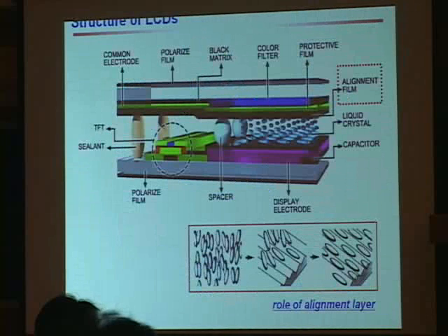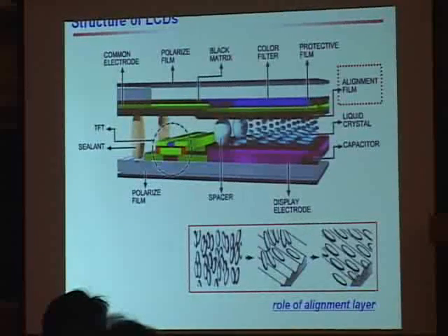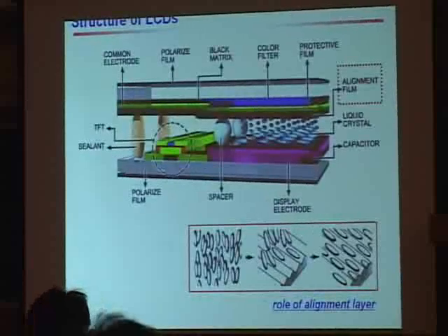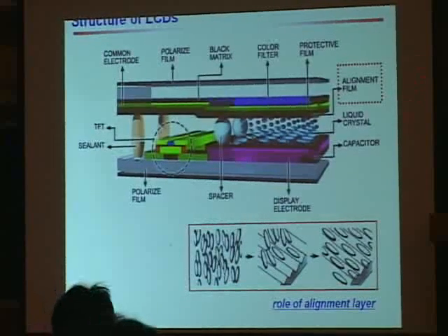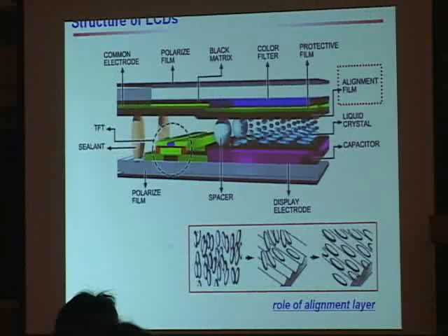If you have a strong and very sharp knife and cut the liquid crystal display panel, you can see this cross section. Today, some presentations talk about the TFT and organic TFT, and some talk about the color filter. But nobody talks about the alignment layer, so it is a good chance to present about it. The alignment layer is very important because it is in direct contact with the liquid crystal and controls the liquid crystal alignment.